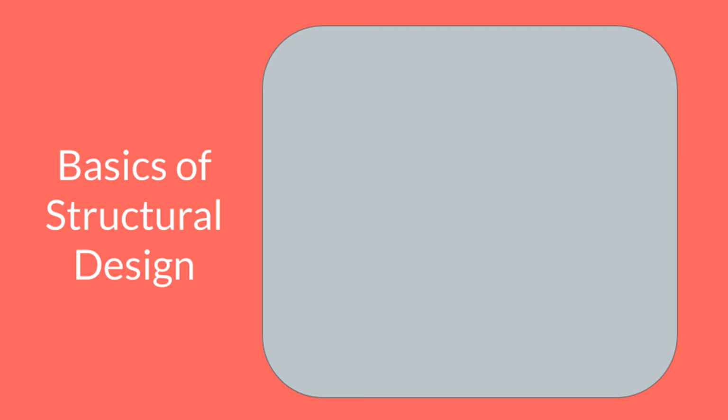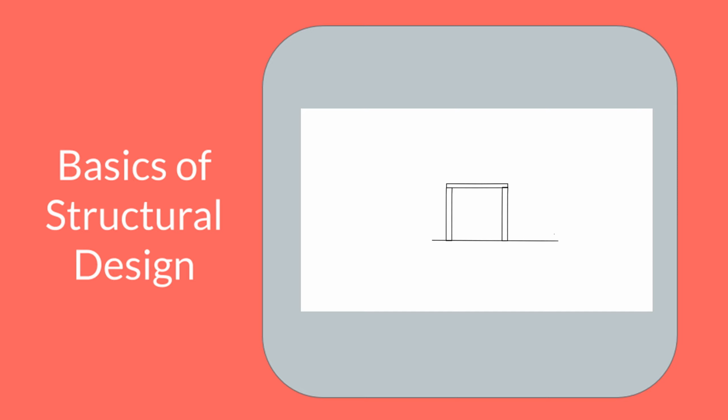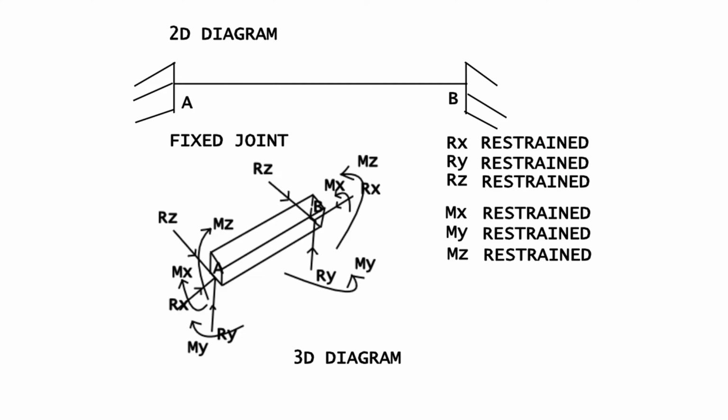Now let us consider the forces as per the members. So we'll start from slab. So slab has bending moment and shear as predominant force, whereas beam has bending moment and shear force. Columns usually have axial force and bending moment as predominant force. Footings have axial force, bending moment and shear force, whereas walls have shear force.